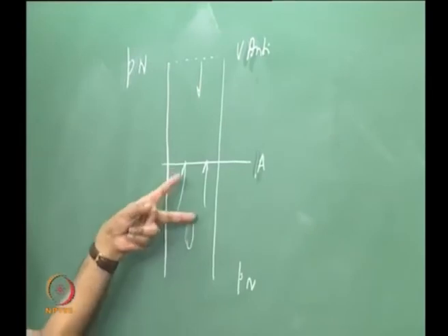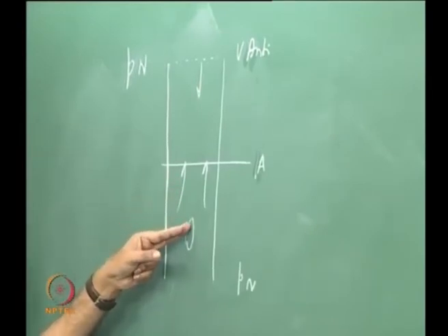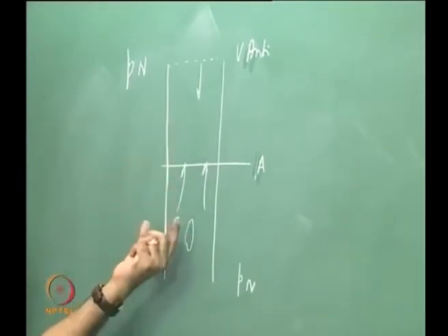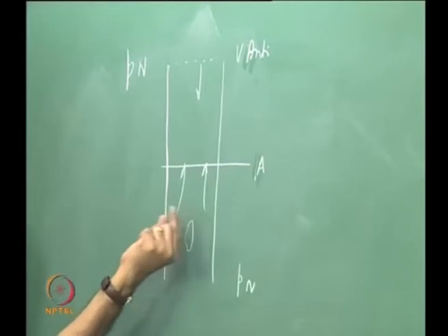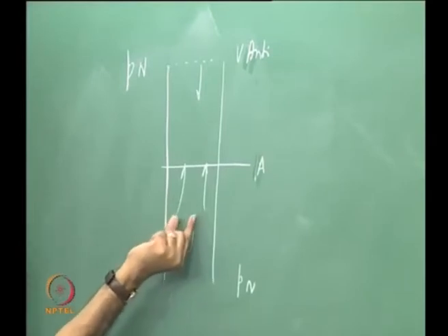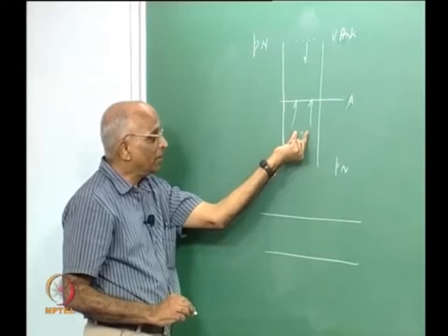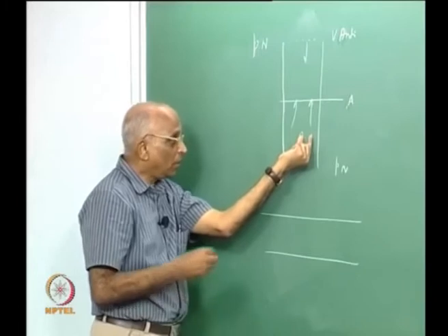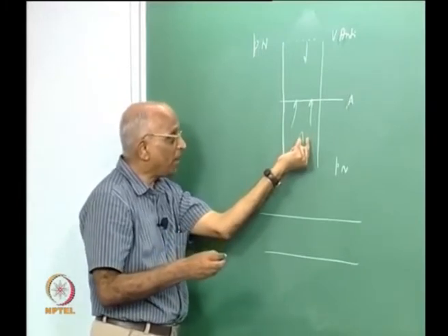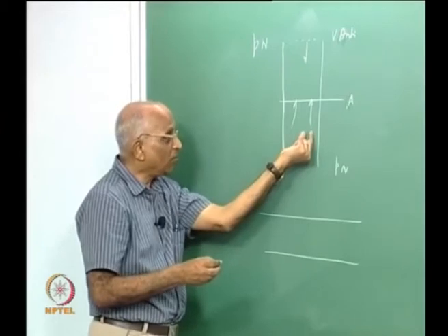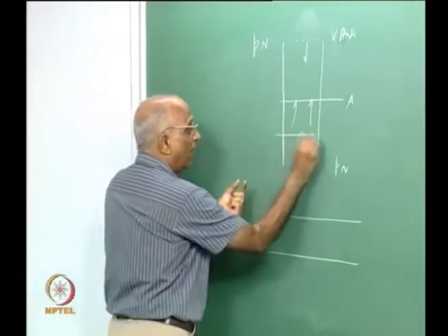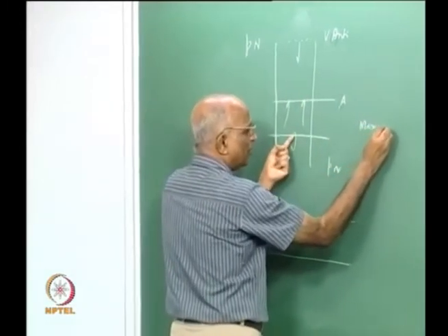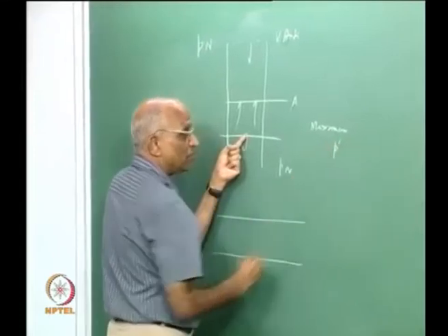At this central place between these two, I still have pressure oscillations and velocity oscillations in the standing wave mode, because my tube diameter is small, I do not give room for the tangential and radial modes, and therefore the location where I have significant velocity, I have lot of energy being added from the sparkler into the flow medium. It is also where the pressure is significant, and therefore at this location when I put my sparkler, I have maximum noise. And what is maximum noise? I have maximum values of pressure perturbation.